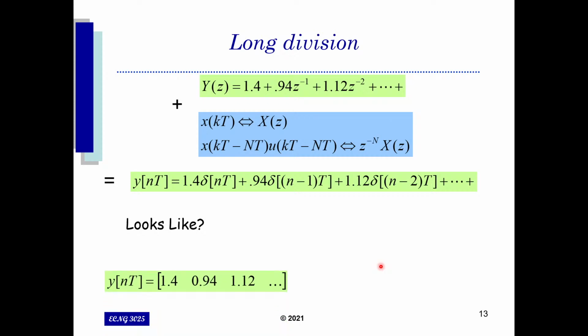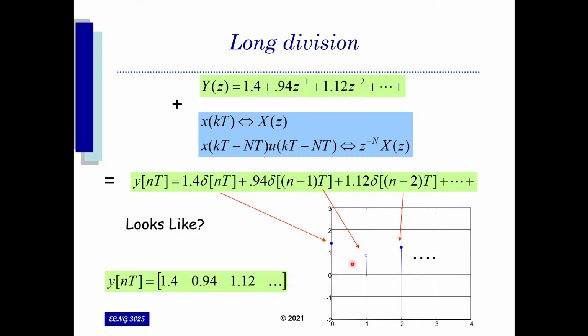What this looks like is just a sequence of values for each one of these terms for the z components, basically a one-dimensional vector that can be plotted accordingly for each n term. So the working for the open form solution or the infinite solution is really in the long division process. And once you have your quotient as your result, you can transfer that immediately using the shifting property of the z transform to obtain the open form solution as required. So this is going to be the easy part once you have the quotient.